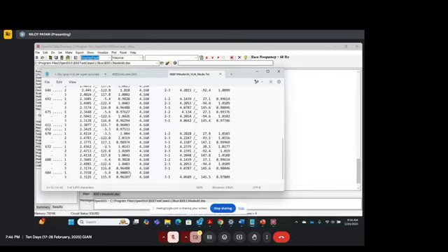There is another standard, not like a standard, but a kind of rule that we follow in distribution systems: we try to keep bus voltages within plus minus 5% of the substation voltage. So we try to keep the bus voltages within that band of 0.95 per unit to 1.05 per unit. So this is in steady state. I'm talking about steady state.